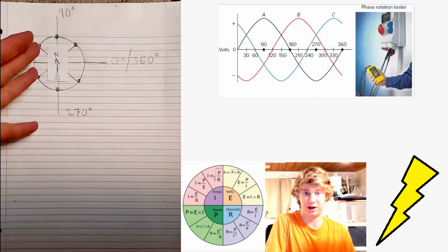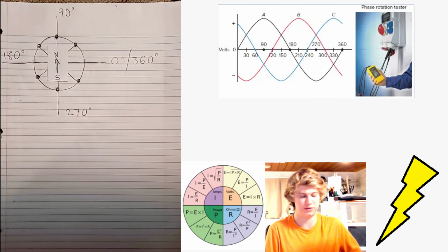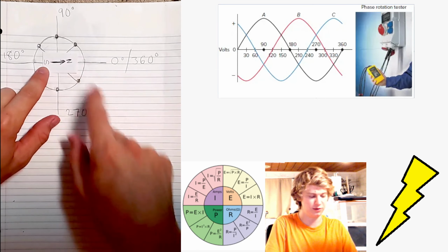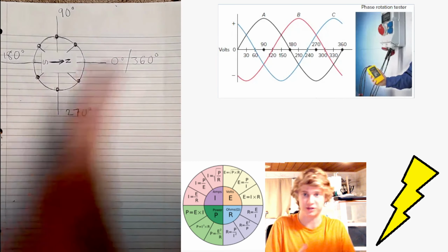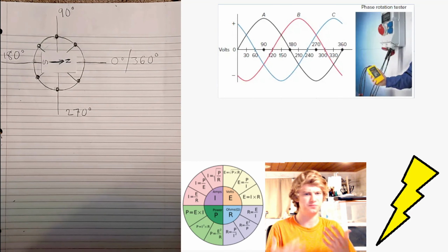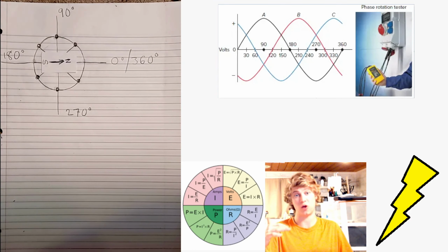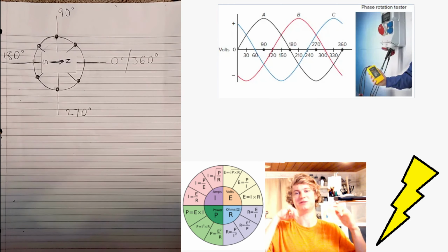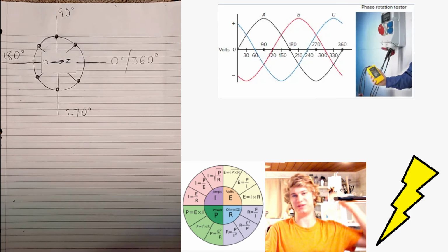And we also think about what we were thinking before with the single phase, but now with the 3-phase and the magnet, we can see that back where we were in the beginning with our 0 point, where the north is facing 0, the south is facing 180 degrees, we can see a few things on our graph. We can see that the A phase would be at the 0 crossing, so no current. You can see right above it, the blue, the C phase would not be at its peak, but somewhere in the middle, halfway between the 0 crossing and the peak.